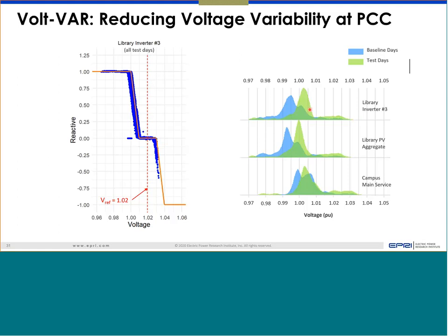And it was effectively doing it, again, the same thing. At the terminal of the inverter it is very effective. It was able to push our median voltage to the right side, and maybe a relatively tighter band also. It was also noticeable at the inverter switchgear panel or the service entry point of the building. Still, it was pushed high and much tighter compared to the